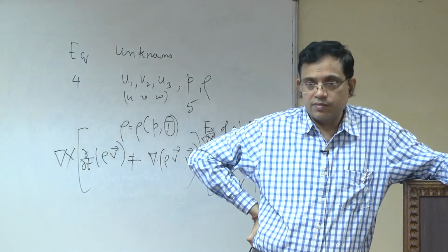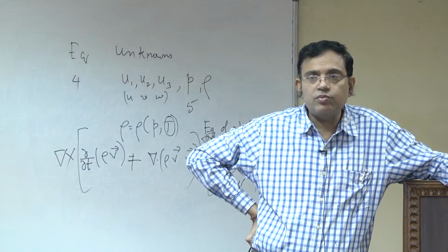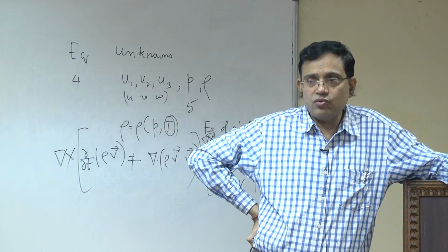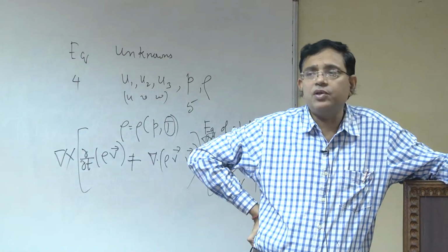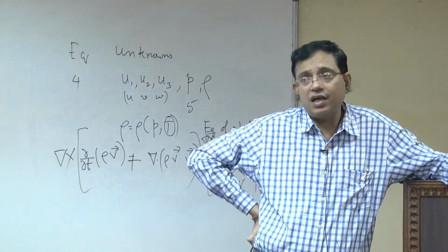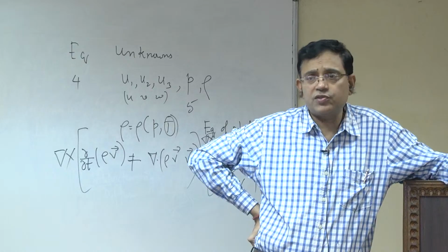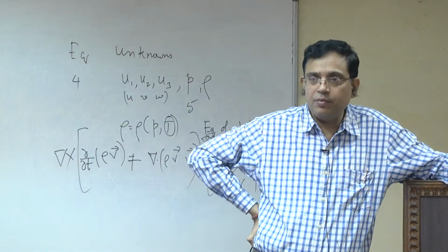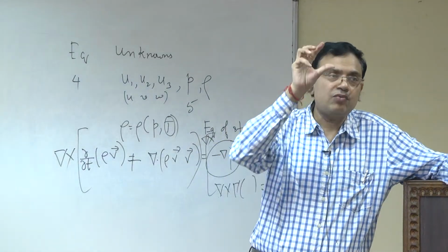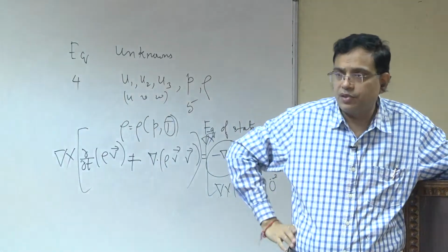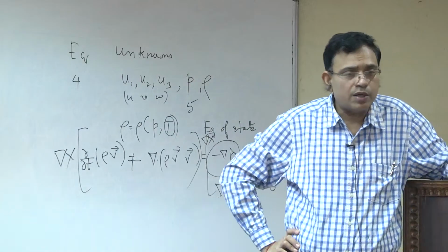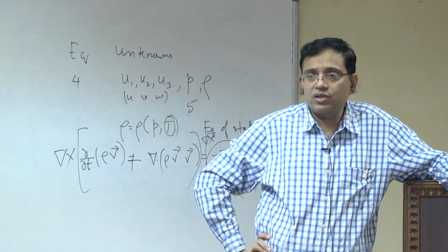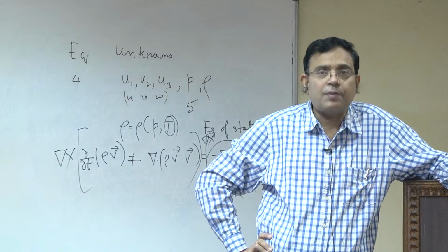Now, where do you get this from? Maybe you have got some experimental data from which you have averaged, that is the best thing you can do, but your experiment will have uncertainty. So, you will have a lot of uncertainty in even prescribing your input, and that uncertainty can spoil your output. If not spoiling, it can give a range of possible errors. When we are doing experiments, normally if you have experimental data we draw an error bar, that is an upper limit and lower limit. CFD people normally would not give an error bar, but that is not correct, because whatever solution you are giving, you should also give a feel of what the maximum upper and lower bounds could be.